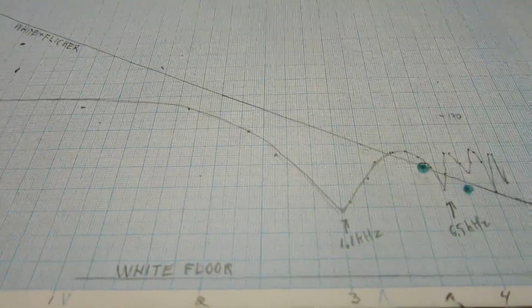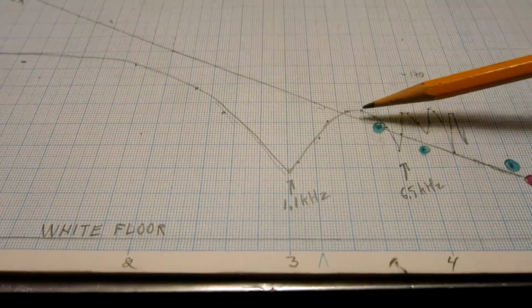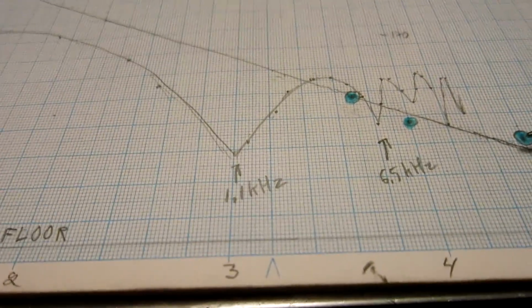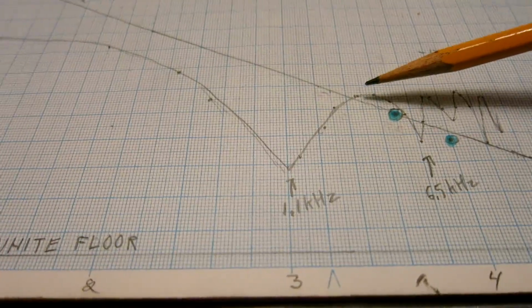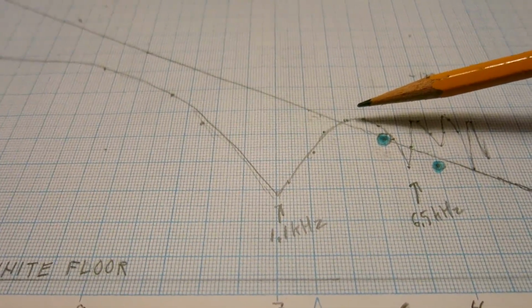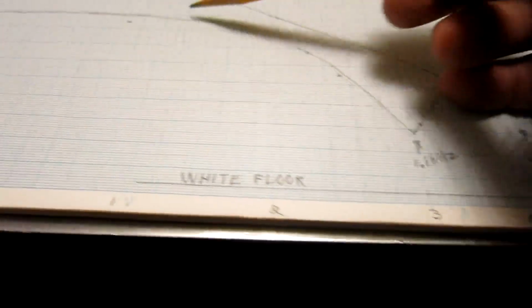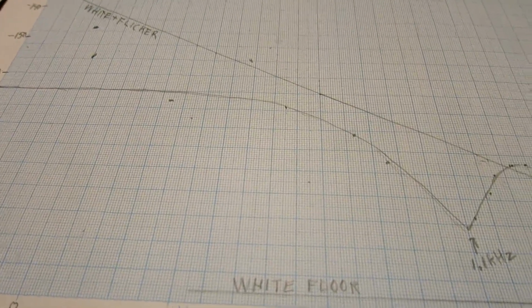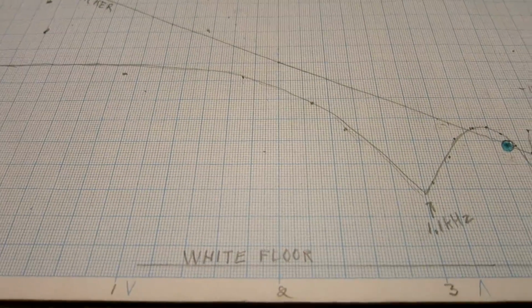When I plot it in the logarithmic scale, I can see that it's not useful at this range, where it was useful to use the notch filter to remove the strong signal and increase the audio gain. But at 1 kilohertz and below that, I should get reasonable results from this setup. So I will have a look to see what comes out.